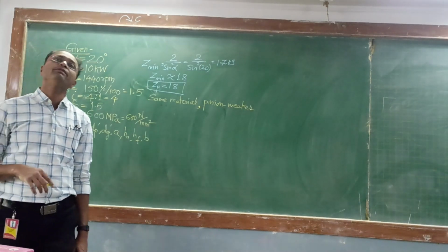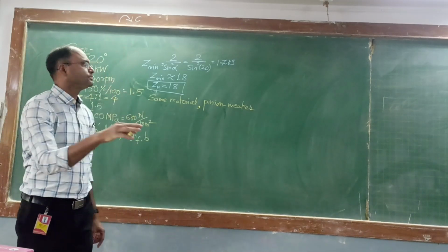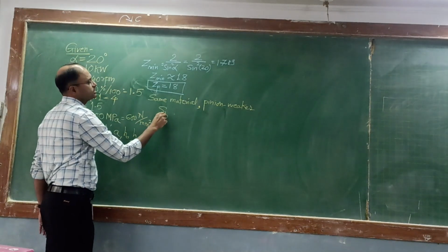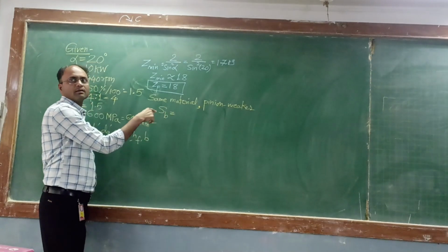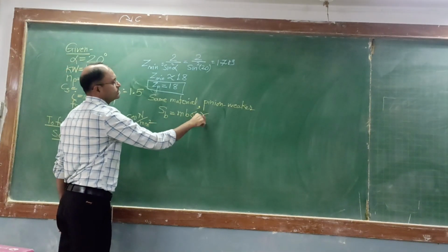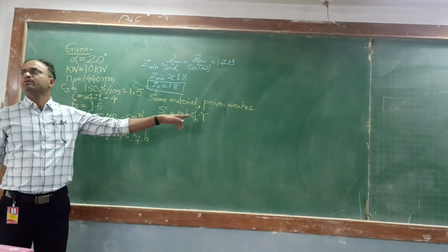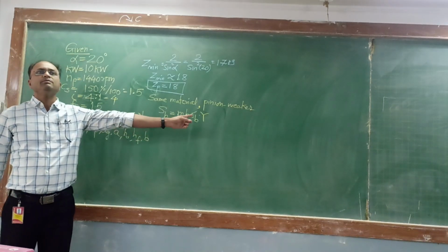No, that is Levy's form factor. I am not asking form factor. Levy's equation is S_B is equal to m into d into sigma_B into Y. This is Levy's equation. This is beam strength. Levy's equation is the equation of beam strength of the gear.